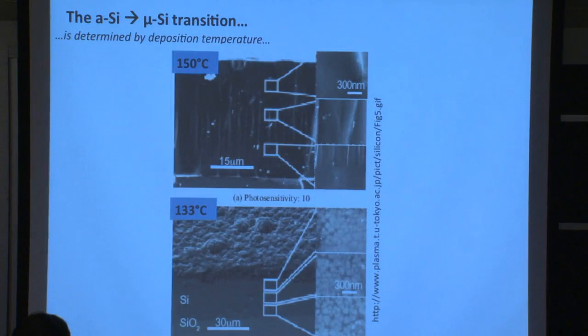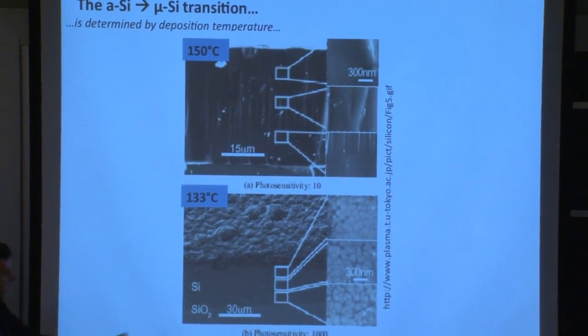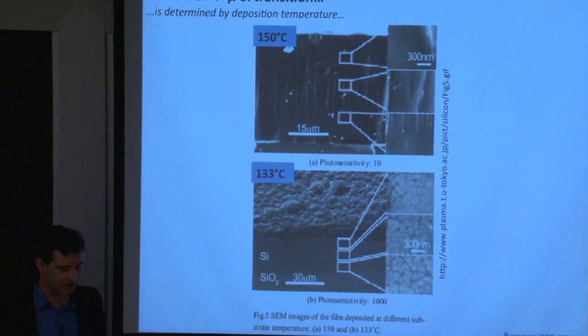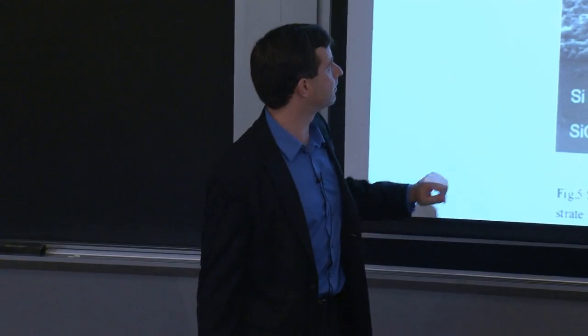So that's, I would say, the essence of amorphous silicon: it's a very promising material, has a wide degree of tunability, but the low hole mobility limits its performance to somewhere around 10% for just a single amorphous silicon layer, and in the low teens for these stacks of multiple materials one on top of another.